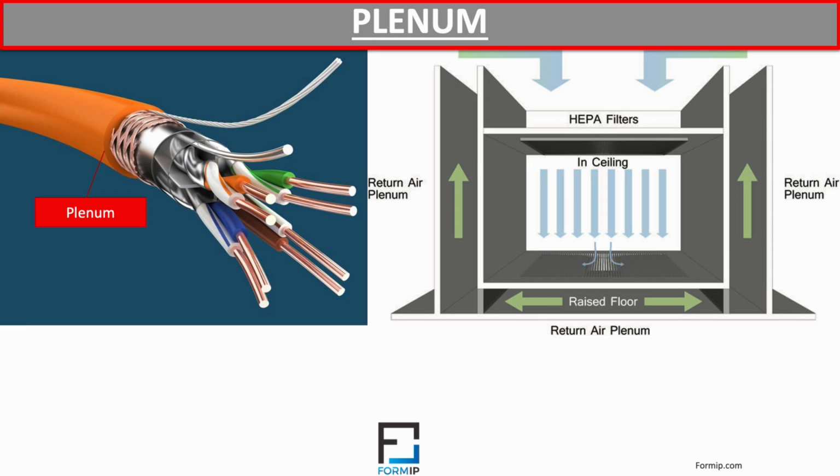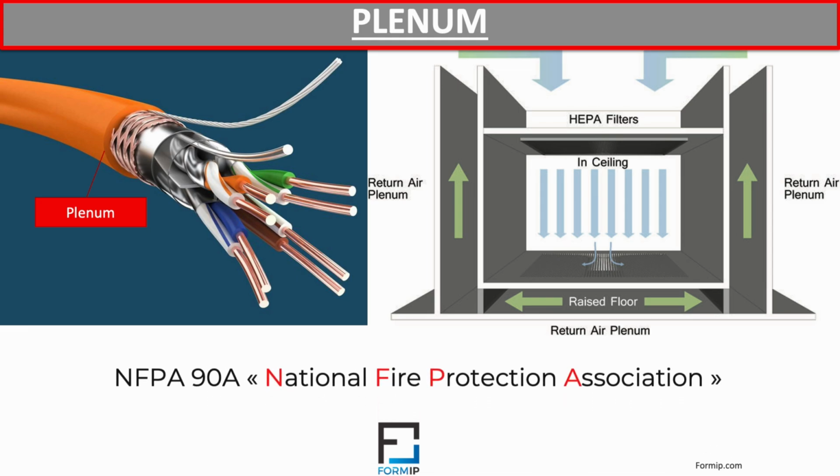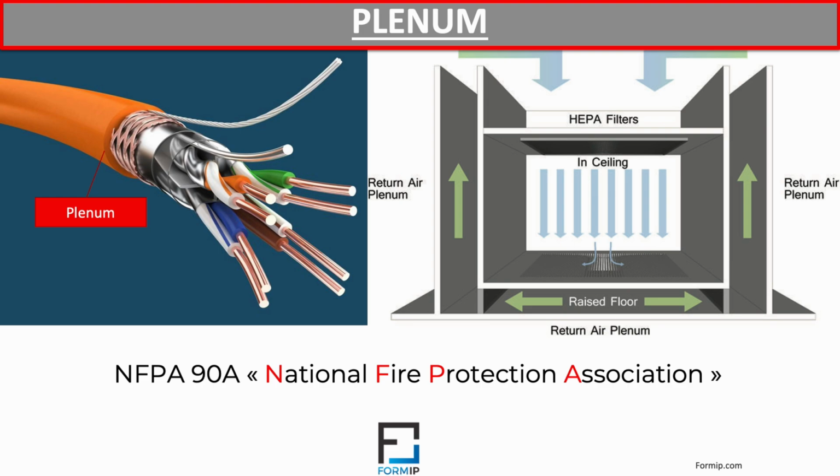For this reason, cables running through false ceilings containing airflow must meet certain requirements. The American standard NFPA 90A requires them to be more resistant to fire and not produce any toxic fumes if burned.